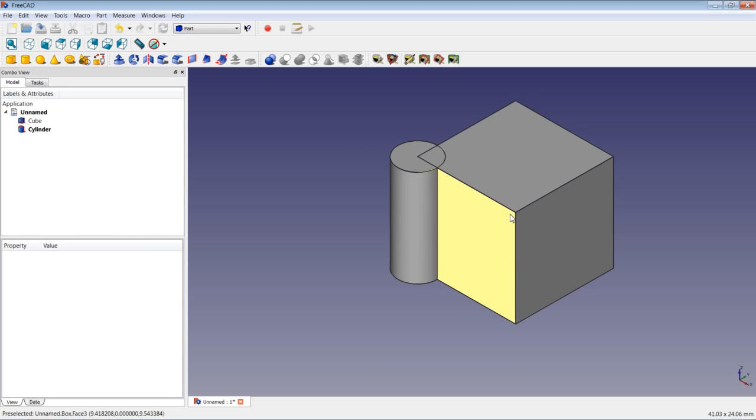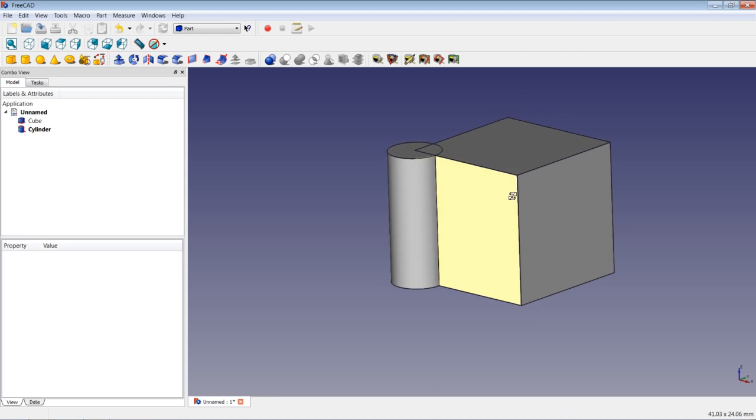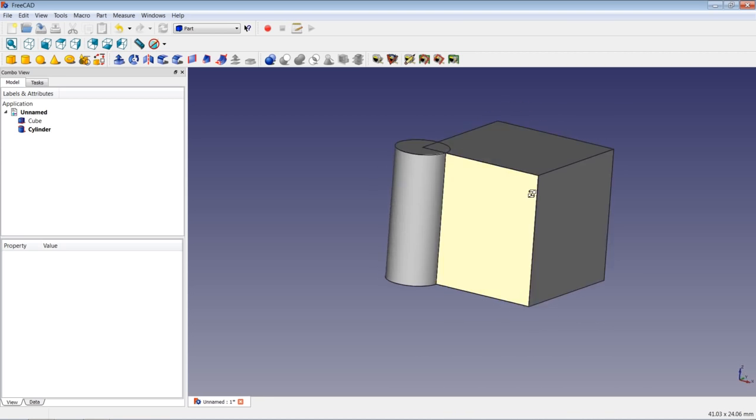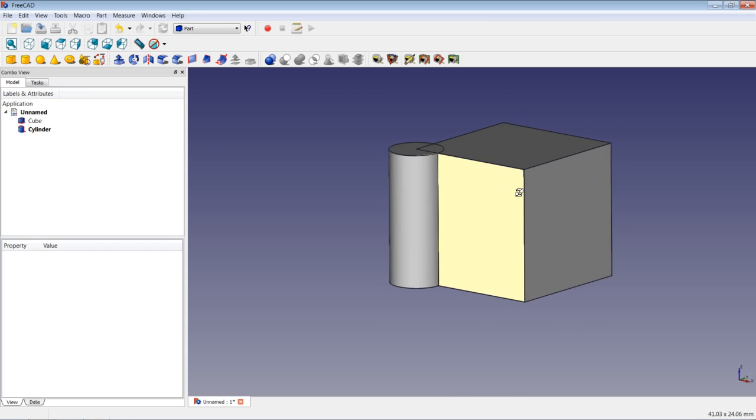If I press the scroll wheel and keep it pressed and move the mouse around, I will tilt the objects presented on the screen. As you can see, the cursor just switched to two tilting arrows. Now I let go of the scroll wheel and show you another operation possible in 3D space.